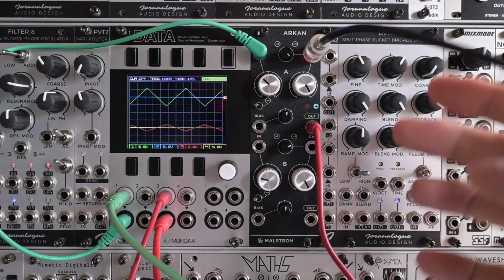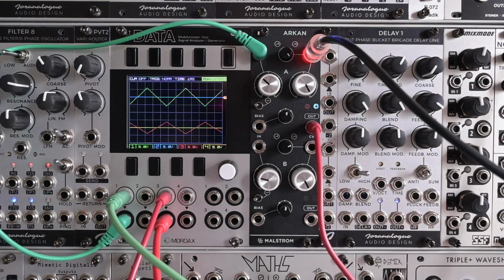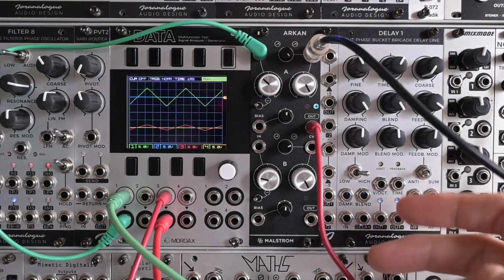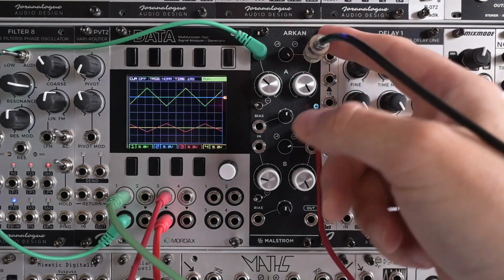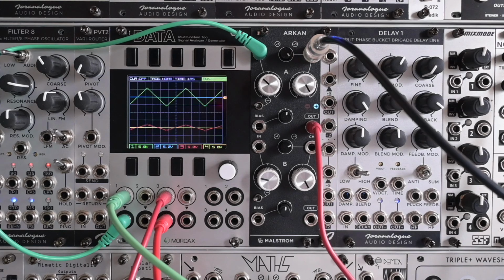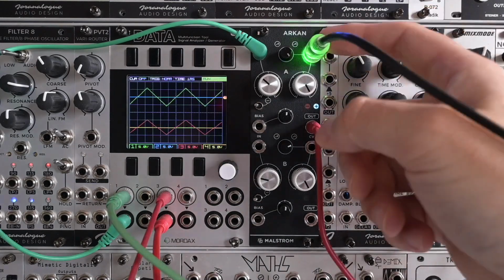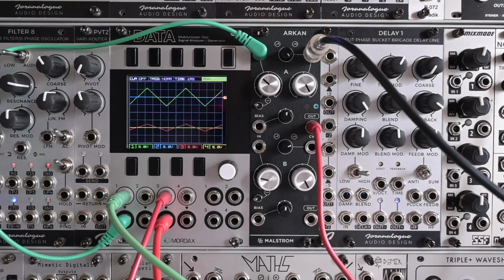Now we're seeing a 4-quadrant multiplier in action, which is just ring modulation. And the difference between a ring modulator and a regular VCA is simply the fact that it reacts to negative CVs here. On a regular 2-quadrant multiplier, the sound wouldn't get through when you're sending in negative CV.